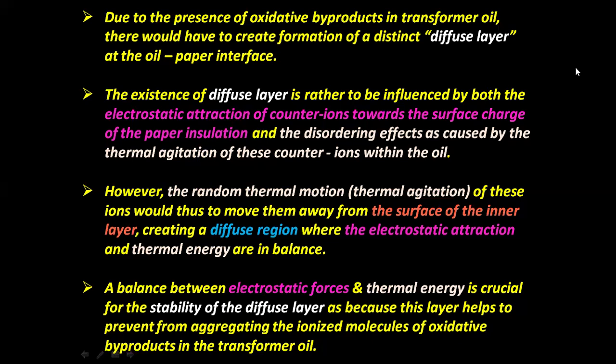A balance between electrostatic forces and thermal energy is crucial for the stability of the diffuse layer, because this layer helps to prevent the ionized molecules of oxide byproducts in the transformer oil from aggregating.